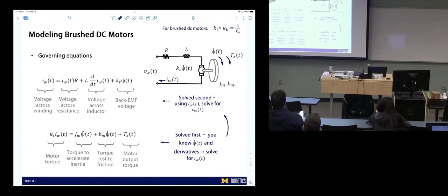What is the difference between the motor's torque and the output torque? So if you were asked a question, like what's the difference between the torque that's coming out of the actuator and the motor's torque that it's providing? Yeah. Well, the motor has to fight other torques from, for example, the viscous loss and the inertia. So you have to take those factors into account when choosing your motor torque because it's going to affect the output torque. Yes. So the motor has to produce the output torque, but it also has to do other things. It has to accelerate its own inertia and overcome the viscous loss.